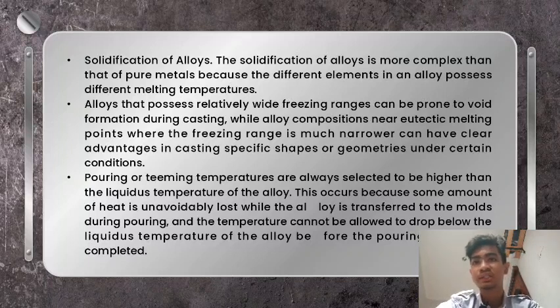For this reason, liquidus temperatures may be obtained from the appropriate phase diagram and used to help establish the correct pouring temperatures for the alloy composition that is selected. There are many methods that can be employed for the melting and casting of metal alloys, and the method that is chosen strongly depends on the type of alloy that is selected and the intended application.